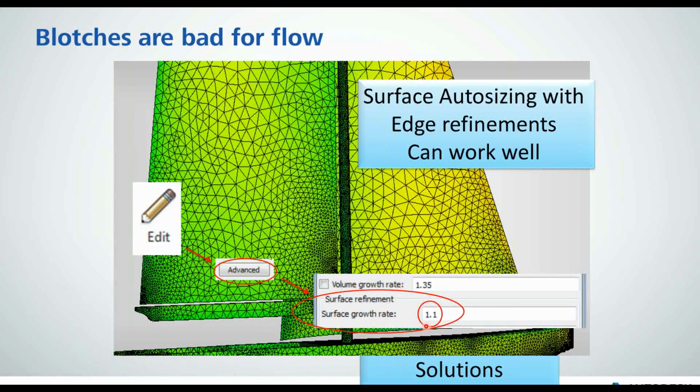By default, it's set to about 1.2. I tuned it down just a little bit to 1.1. What this allowed me to do is that these areas that were very finely meshed will grow as they propagate to areas that are larger sections of the surface. By turning that down, it had a smoother transition to these larger areas.